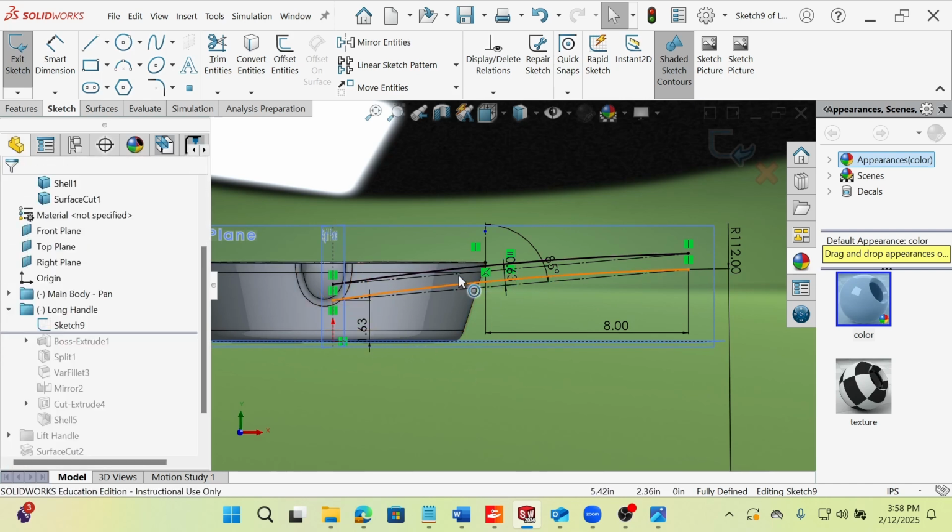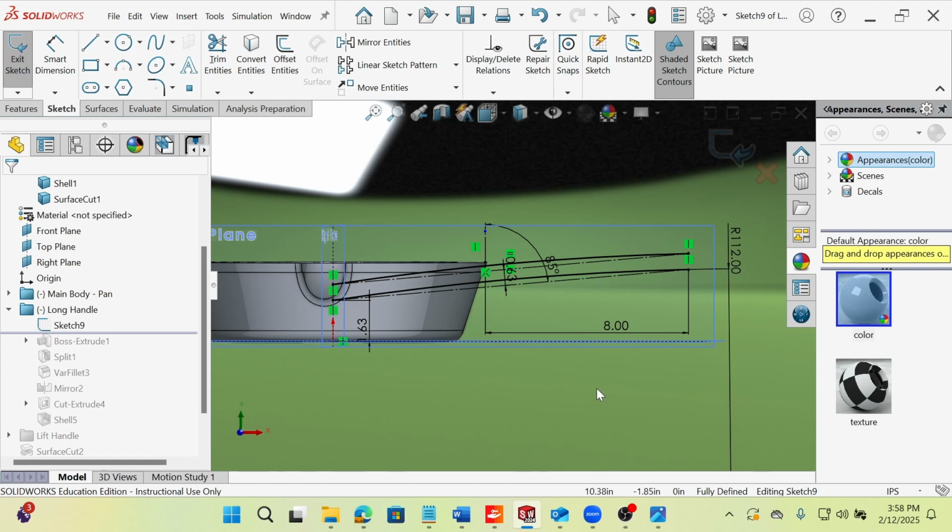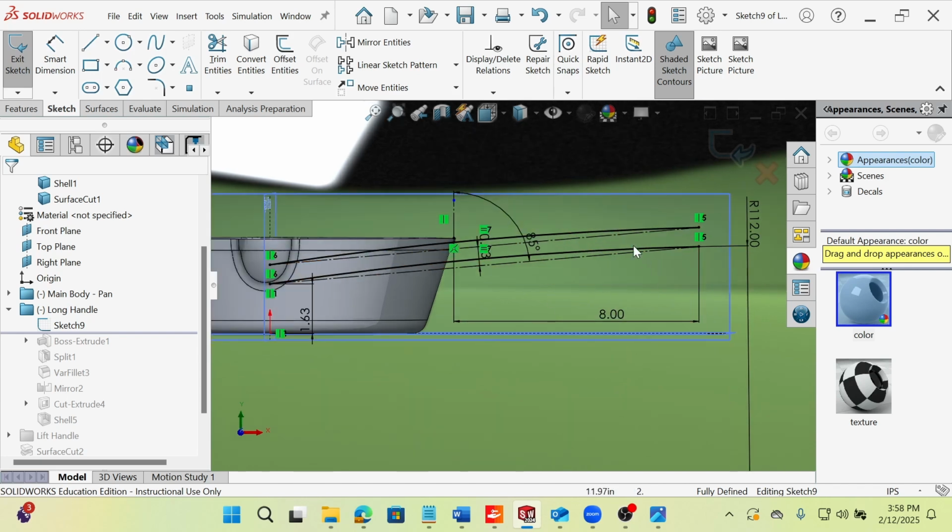And then I just added a 3-point arc here to use as the actual, kind of defining lines for the handle. The straight just seemed a little too aggressive, a little too straight and unfriendly. So I do like to use them as an underlay, like a reference point to define some angles and use that way.